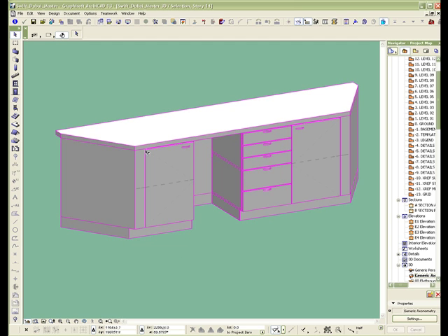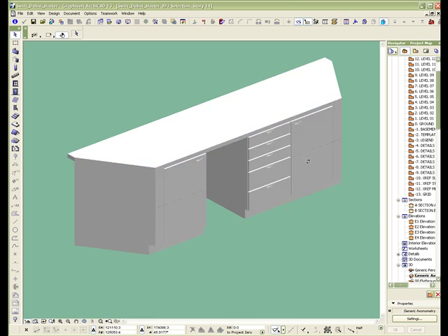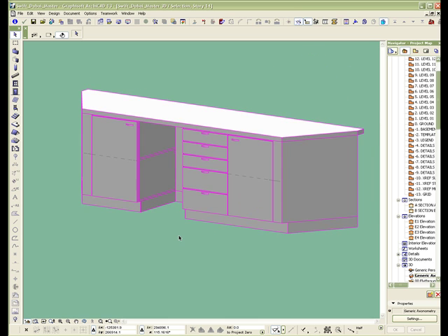With a combination of the flexibility of the configuration of this library part, its ease of use, and the representation of elements such as shelves and door swings in the elevation views, creating joinery elements and documenting these elements is fast and easy.